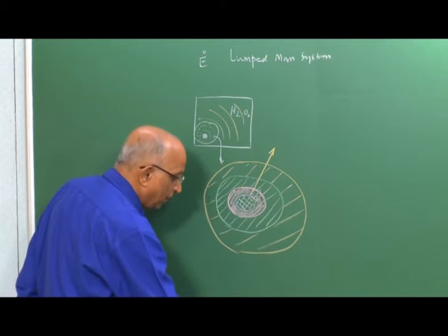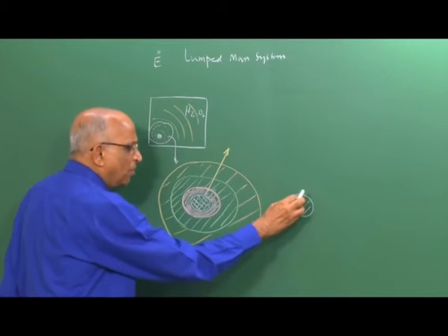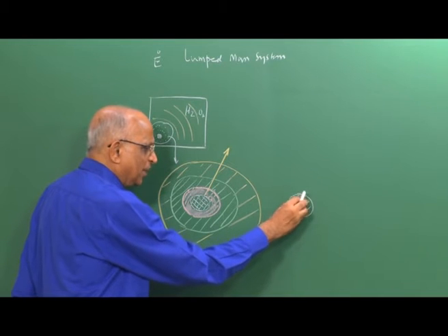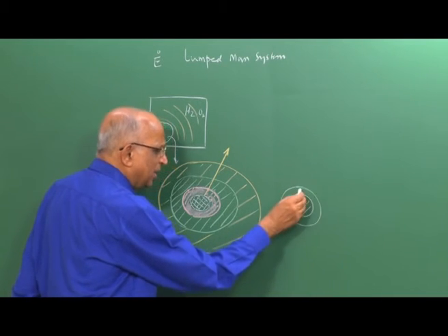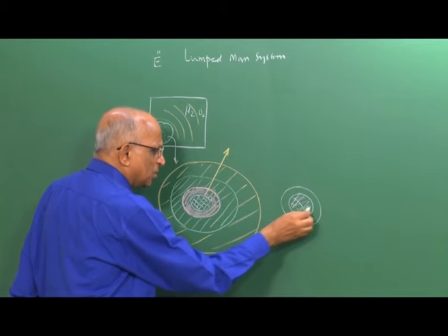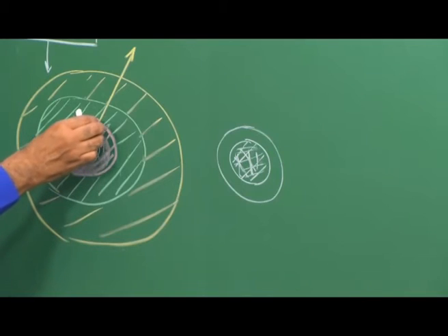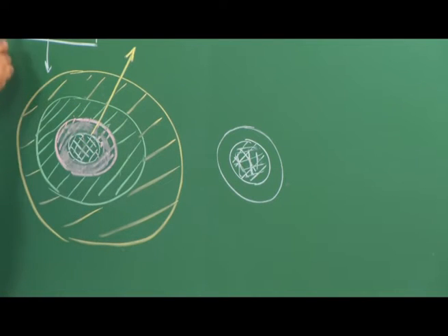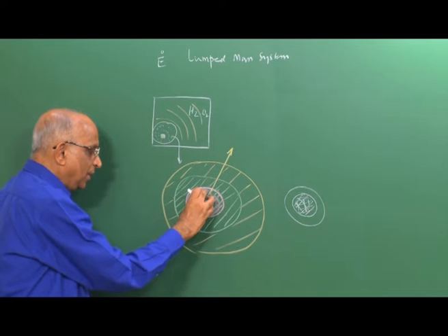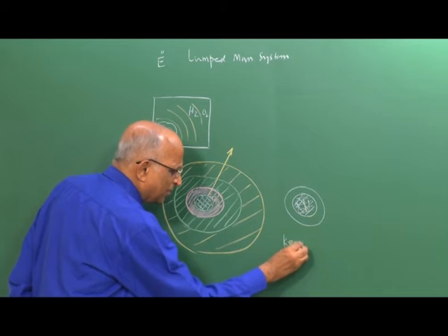This initial volume, which I showed something like this over here, the amount of heat in it will collapse, or the temperature in it will decrease, chemical reactions will decrease, and by the time the neighboring element gets heated up, it is inadequate to heat the neighboring element and it collapses. Therefore, the spark or the chemical reaction collapses and I can no longer get combustion occurring in the neighboring layer. Therefore, we say, well, I use a spark for igniting a mixture, and unless I have adequate quantity of this particular volume, or let us say by volume I mean something like a kernel, something like a seed.